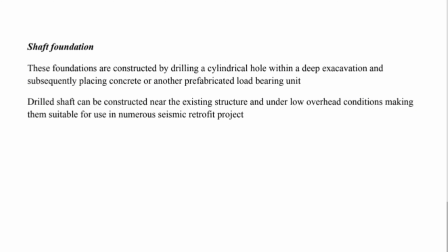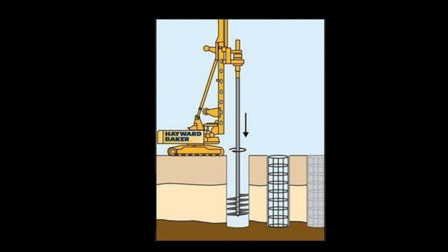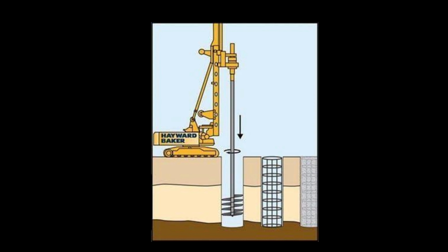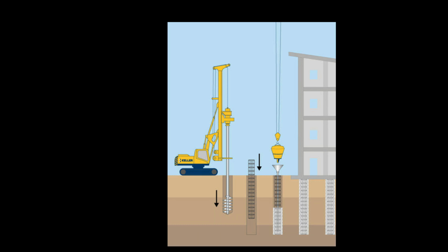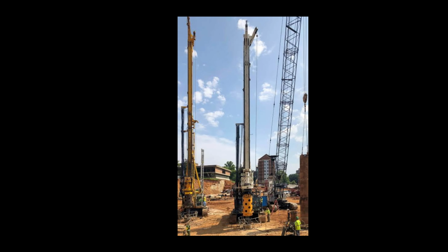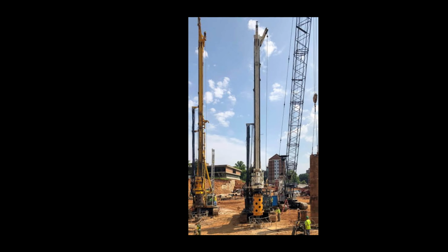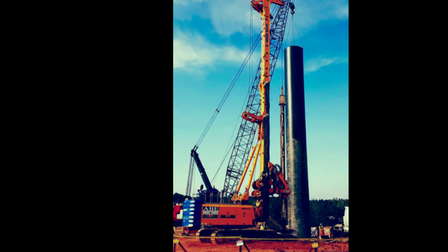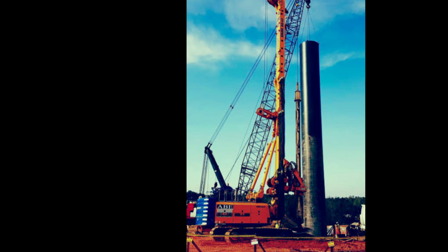Shaft foundation. These foundations are constructed by drilling a cylindrical hole within a deep excavation and subsequently placing concrete or another prefabricated load-bearing unit. Drilled shafts can be constructed near the existing structure and under low overhead conditions, making them suitable for use in numerous seismic retrofit projects.